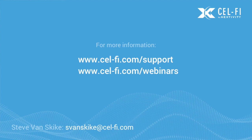So the MIMO panel antenna is used for either the 1000 or 2000, and the reason is because there's two RF ports on each. You're certainly getting MIMO as the connection if you're using a Quattro 1000. The Quattro 2000 is a SISO antenna, but you're still making use of both of those antennas, and it has to do with the hardware architecture of a 2000.